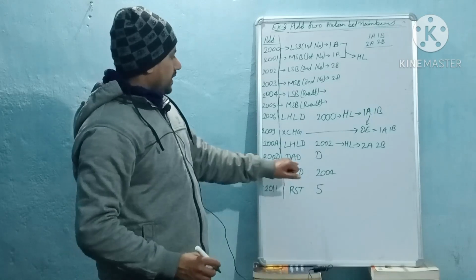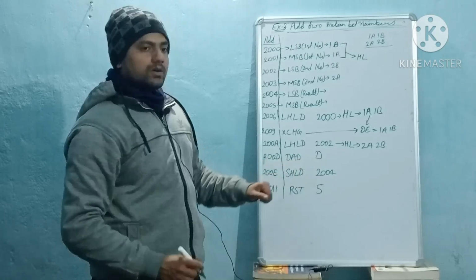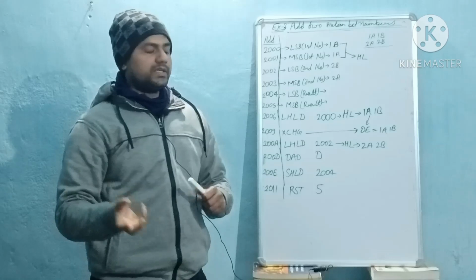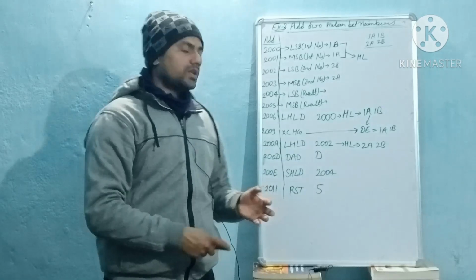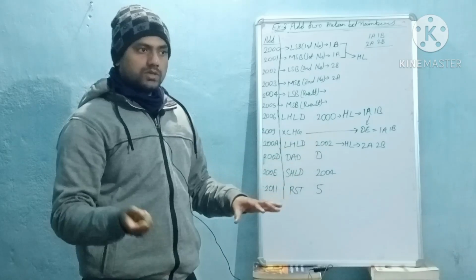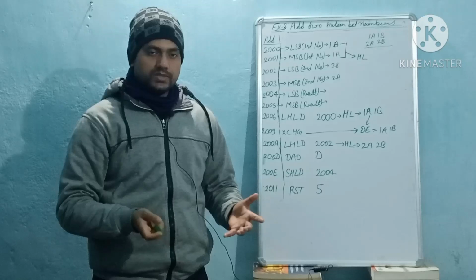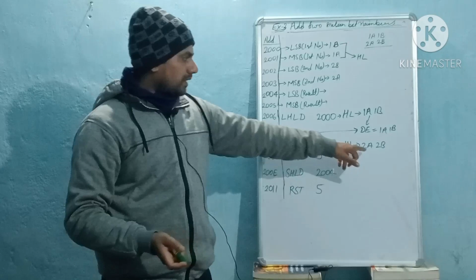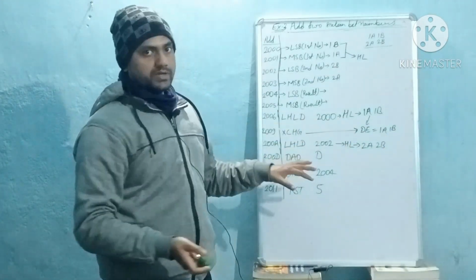Okay. Then after that, written DAD D. This instruction adds. Earlier, for the addition of two numbers, we used instructions like ADD, which used the accumulator to save the result. But here the result is 16 bits and the accumulator is only 8 bits, so the result cannot be saved in the accumulator. That's why this instruction is used. It adds these two 16-bit numbers and the result is saved in the HL pair register.